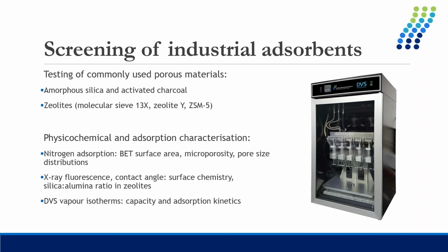So the initial stage of this project, we worked on screening a number of industrial adsorbents. So we looked at amorphous silica, so silica gel, activated charcoal, and 3 different kinds of zeolites. We have hydrophilic molecular sieve 13X and high silica forms, so hydrophobic forms of zeolite Y and ZSM5.